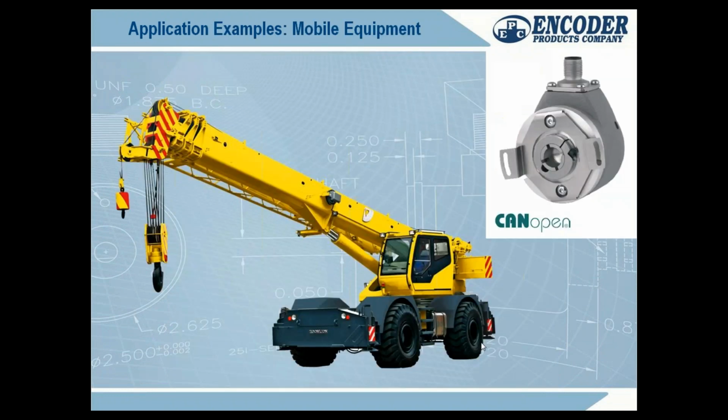Mobile equipment, again, this is very similar to a crane I'm working on right now. A lot of CANopen in the mobile industry. CAN bus is pretty much it for any kind of mobile equipment. And this encoder is installed on the drive gear that turns the superstructure of this crane here. So there's a ring gear in here on the superstructure, and then we've got a drive gear that's running and it spins this crane.